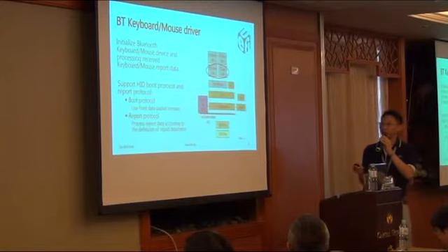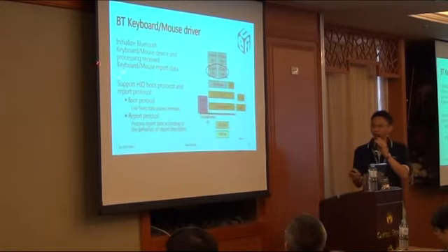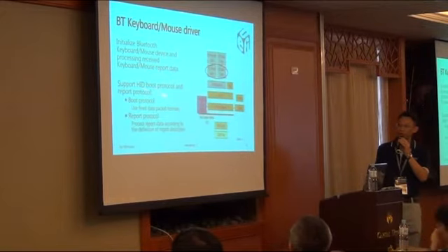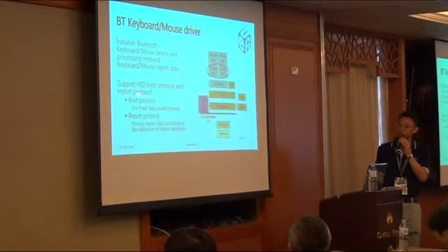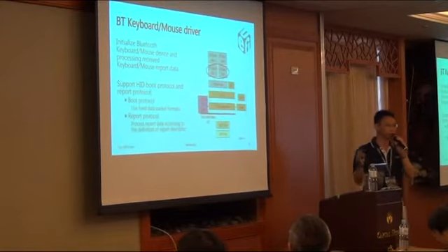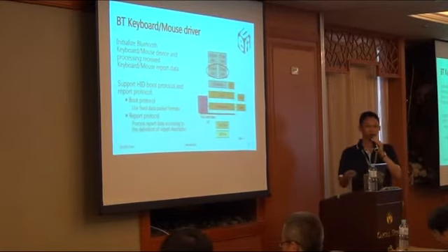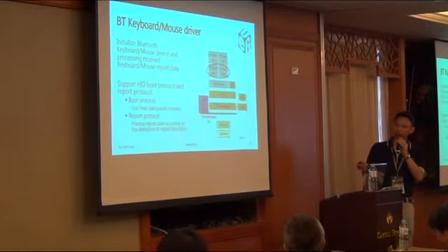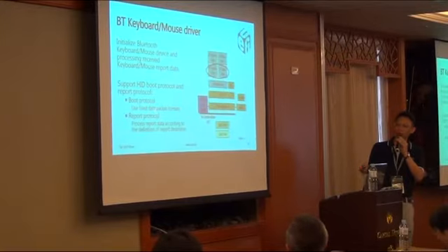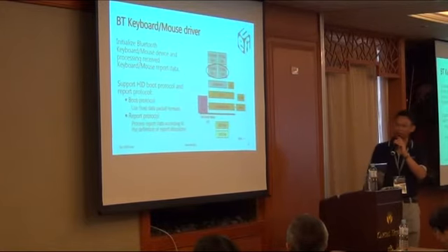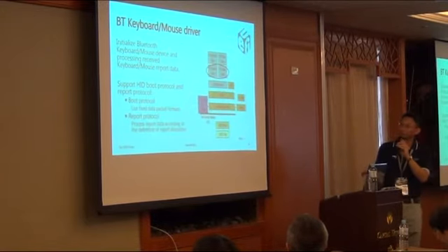So in the Bluetooth keyboard and mouse driver, what it does is support the device setup request. It also parses the input data, and also supports the HID boot protocol. This is the same as a USB class device. The USB HID device also supports the boot protocol and the report protocol. For the boot protocol, it's a single transfer packet. You don't have to parse the report packet and descriptor to know the report data.